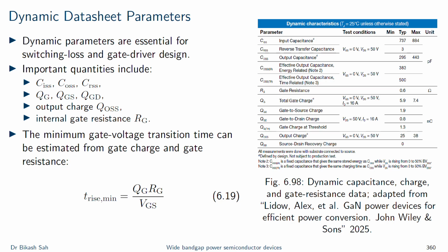The datasheet that you see in there shows the dynamic properties. So this is a simple estimate, I would say, but it's also very useful. But you have to remember that real switching also involves driver resistance, external gate resistance, package inductance, source inductance, load current, DC bus voltage, and nonlinear capacitance. For GaN, dynamic parameters are often more important than static parameters because converter benefit comes primarily from fast switching. A device cannot simply be selected properly without an understanding of QGD, QOSS, and CRSS, I would say.